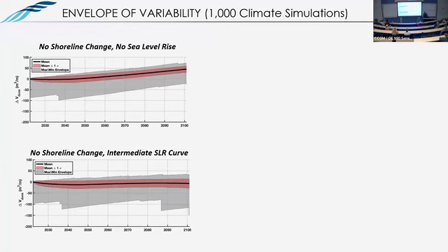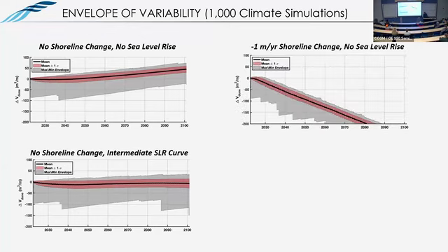And we can add things like shoreline change rates. And what we see is that if we have a negative shoreline change rate, this really imposes what's going to happen in the future. If you have a rapidly eroding shoreline, there's really no way to keep a dune in place past decadal scale. The beach is highly coupled to what the dune is going to do.